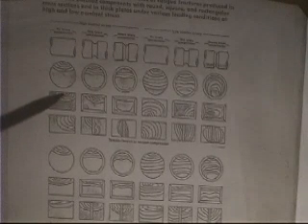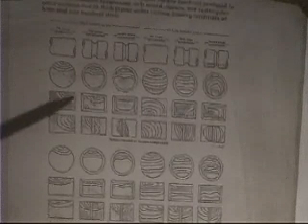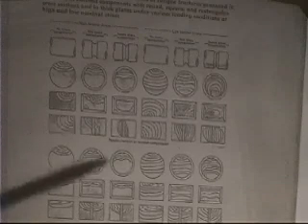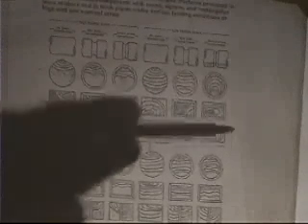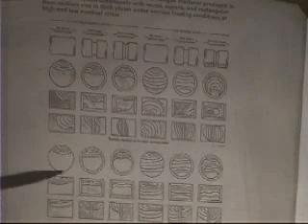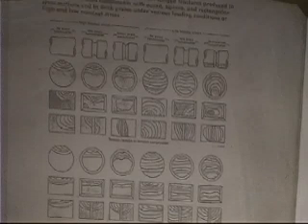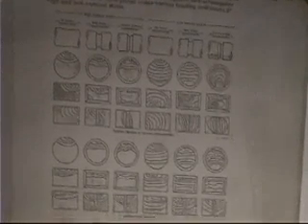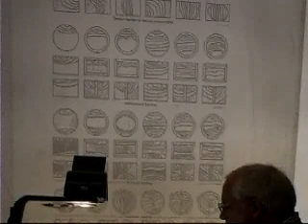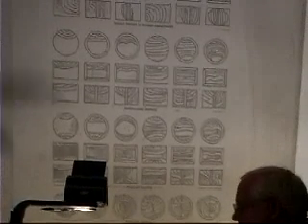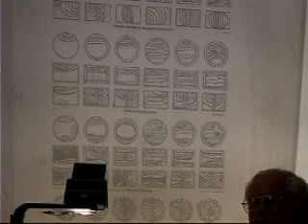It turns out there's not a big stress concentration. It's a fairly high nominal stress, and it is a rectangular part, and it looks something like this. Now, some of them start at a corner. This is tension, or tension compression for all of these. Down here, you're going to have unidirectional loading from one side. Here you have reverse bending, okay? So you're going to actually have a fatigue crack start on this side and also on this side, and they grow together here in the center, and this would be in torsion, okay? And without going through each one of these, each fatigue crack will have a different pattern.